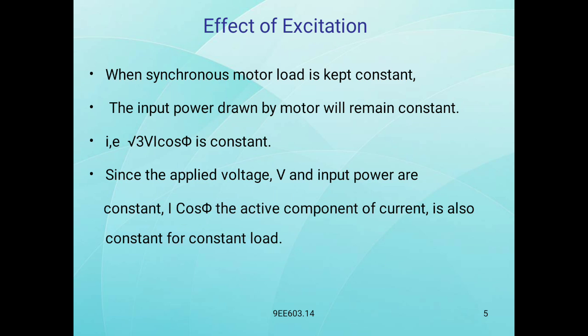So now, here is the effect of excitation when the synchronous motor load is kept constant. That means the load is constant. There is no change in load variations. So that means power is also constant. Here the input power drawn by the motor will remain constant.